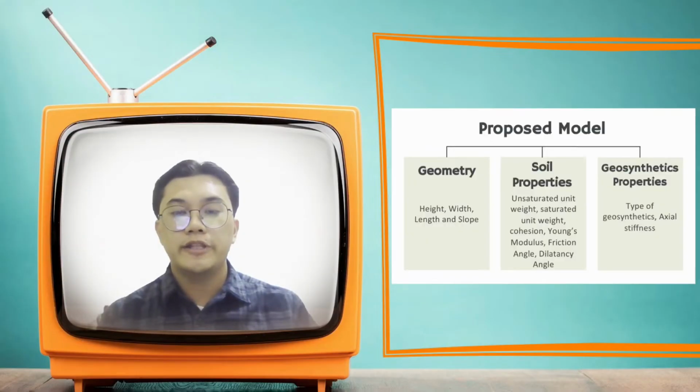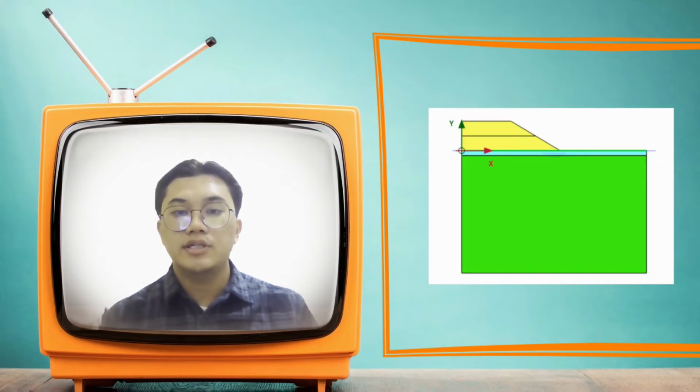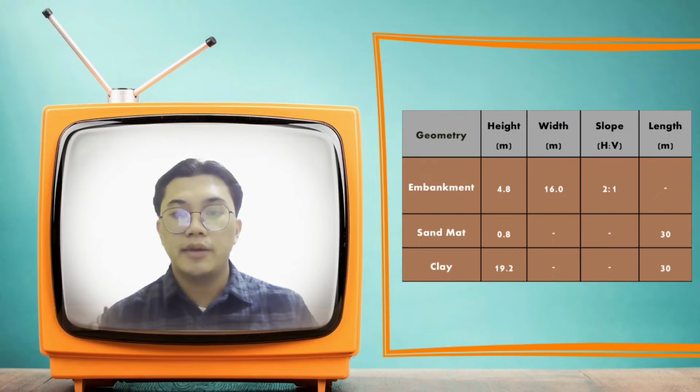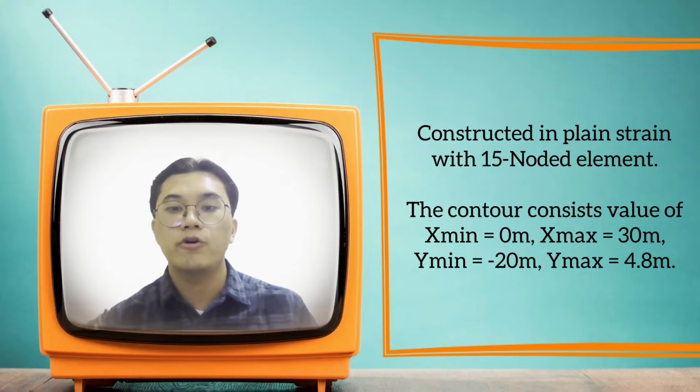In the proposed model, there are three things to be highlighted, which are geometry, soil property, and geosynthetic property. The first one is the geometry. Each of the materials in the geometry, such as embankment, sand mat, and clay, has its own specific height, weight, slope, and length. In this project, the material is constructed in plane strain with a 15 noded element. The contour consists of x minimum of 0 meter, x maximum of 30 meter, y minimum of negative 20 meter, and y maximum of 4.8 meter.